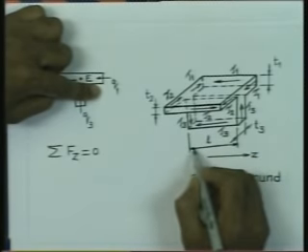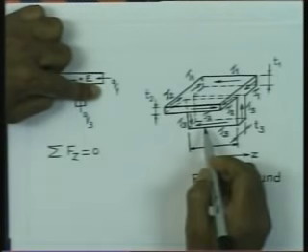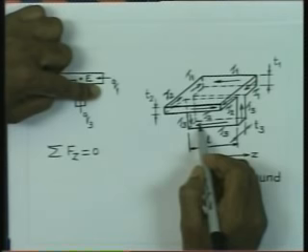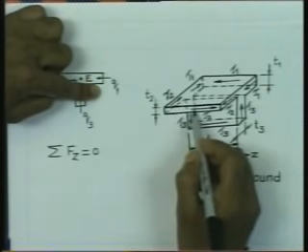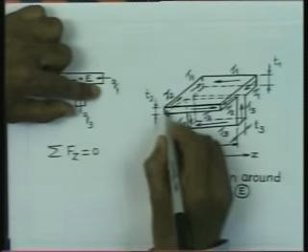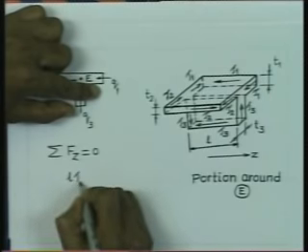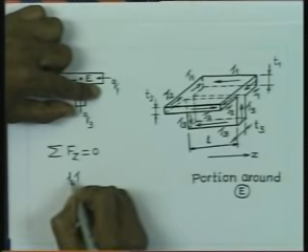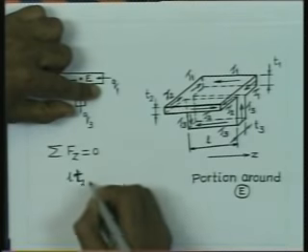Let us say that the length of this segment is equal to L. So, the forces are going to come from this bottom face, this face at the back, and this is the third face which is at the front. Let us now write this area is L into T2. So, L into T2 is the area, and the intensity of the stress is tau 2.